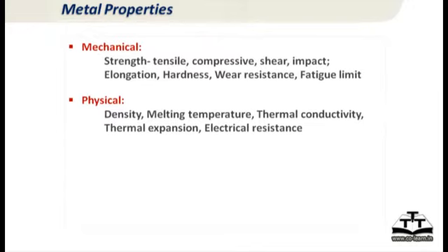So for example, density at liquidus, density at solidus, density at pouring temperature, density at ambient temperature, you need to know the values. Okay, otherwise you do not know what is happening to the casting and the mold. Similarly, thermal conductivity, specific heat, even your thermal expansion which controls your dimensions, these are important physical properties that we need to know. And these values are not available for detailed alloys.